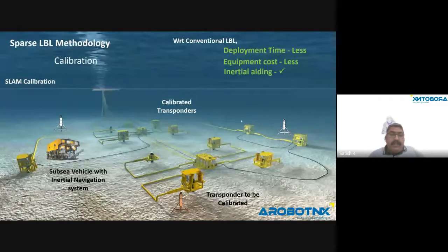With these 2, I am going to find the unconstrained transponder, which has moved out. I take these 2 references along with an INS and a solid DVL, compress everything together, do the initial calculations, and tell it, okay, I am very much stronger now, from here I know where you are. This is what is called SLAM.